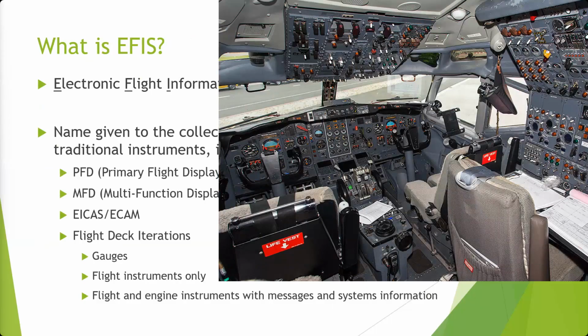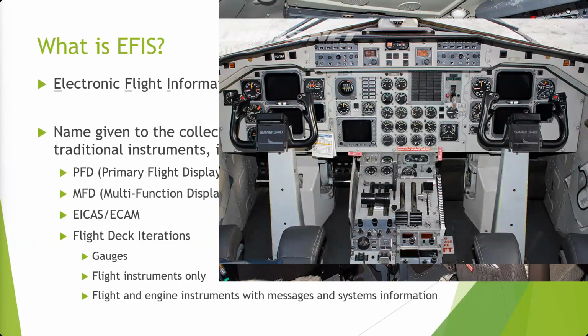And then this also has flight management systems, the computers for programming navigation on each side. This doesn't have a separate FMS. Actually, it does have one, but it's built into the primary and secondary flight display, the EFIS system.